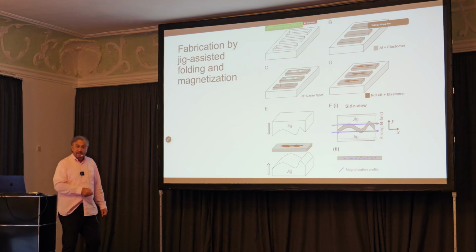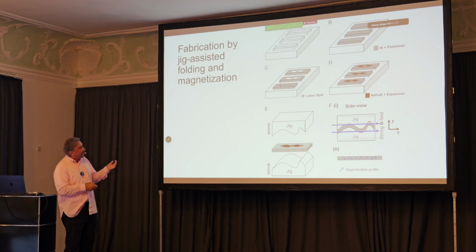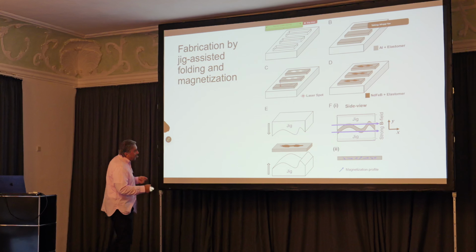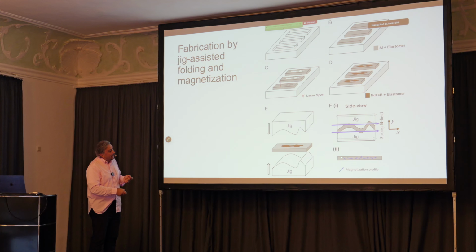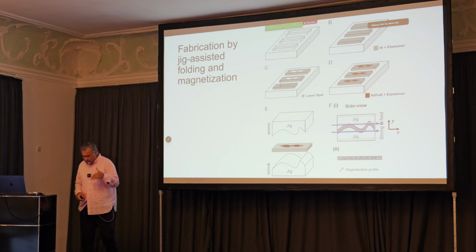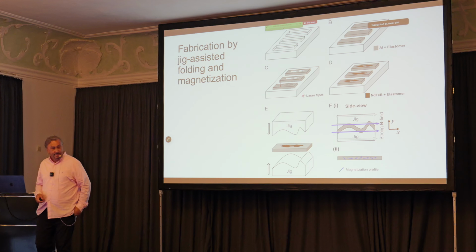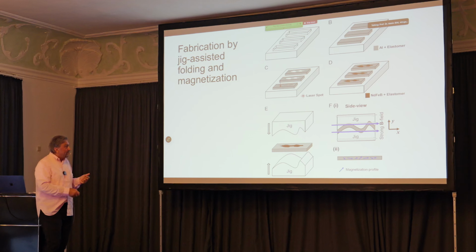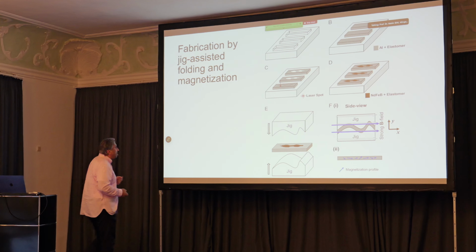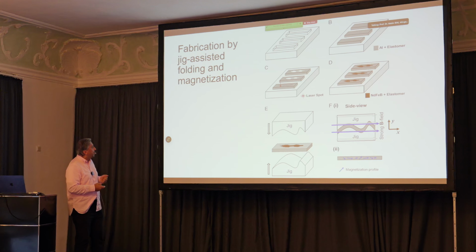And why do I cut the black magnetic part in different areas? Because if I want to change the magnitude of magnetization locally in the given length, I can make more material, that means more magnitude, less material, less magnitude, no material, zero magnetization. So that way you can precisely program the magnitude by the area of the black part and the orientation of the magnetization by the deformation of the jig. So it's again a solved theoretical problem, and you can fabricate it. So basically we can create anything one-dimensional in this kind of profiles that we want and optimize from the algorithm.